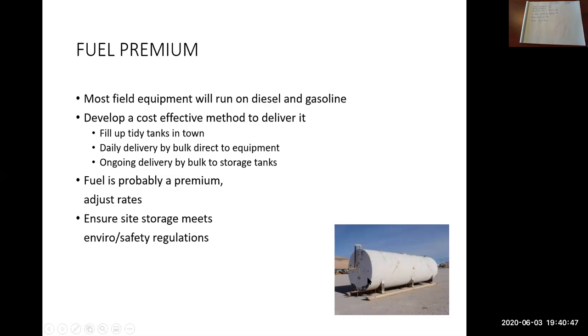If you're going to do a site storage operation like this, what's shown in this photo would definitely not be allowed. It looks like probably a 10,000 liter tank, maybe more. It's kind of hard to tell the scale. It's got no containment around it.